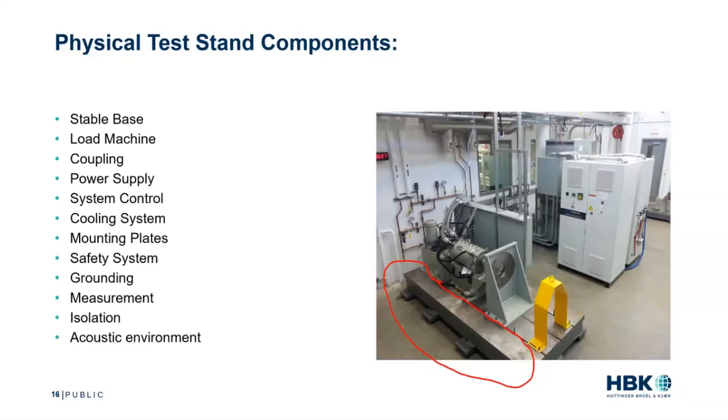And even how it's mounted to the floor. In this example, our floor was not completely isolated, so we have these little isolation pads. But a lot of people will pour an independent slab where they actually have a slab of concrete that's cut out of the floor that the base is mounted to. Again, just to give us that really, really large mass to ground our test to. And then we're not transferring things like vibrations to the building.